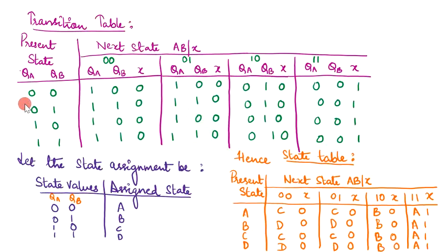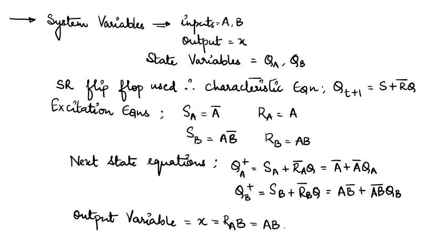these. So how we are going to do that is, QA is 0, A and B is equal to 0 0. Okay, what is it going to be? QA plus. So you need to substitute for A and B and find out what is the value of QA plus. In this particular expression, B is missing, so you can forget B. Just A bar is very much essential.